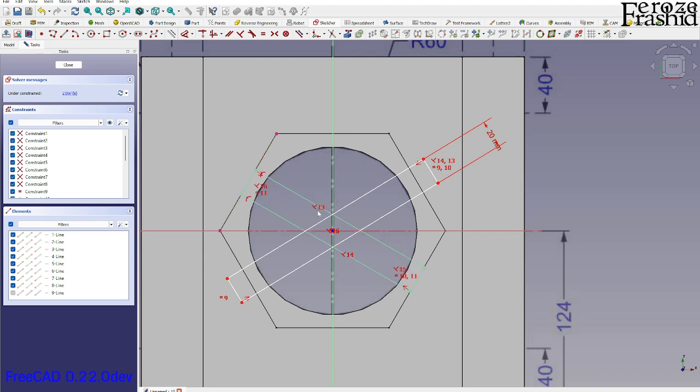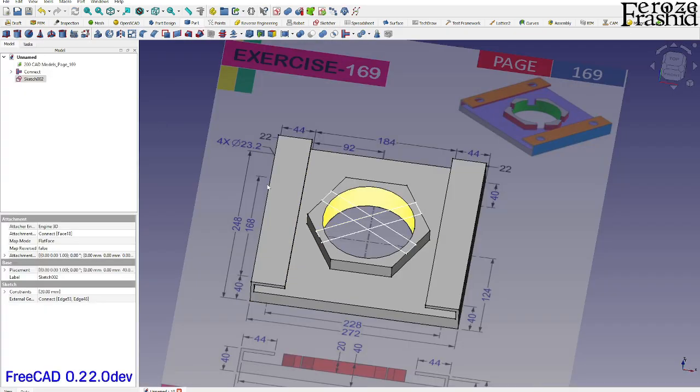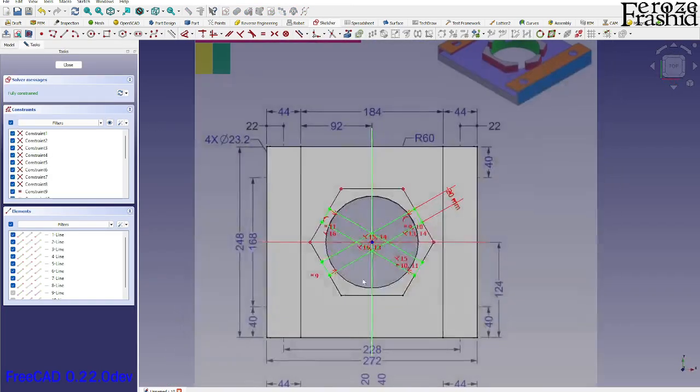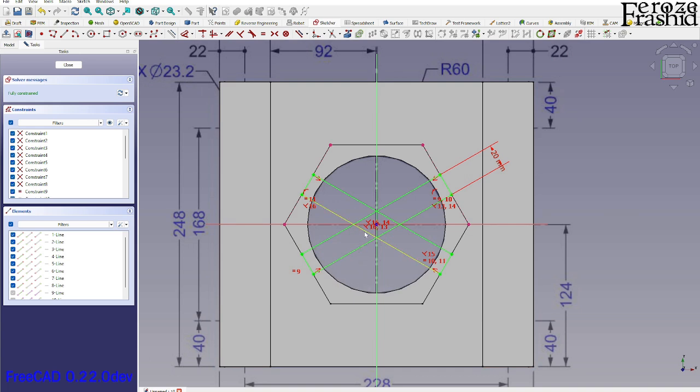Okay, see how it lined up. So maybe we need this reference line as well, and place these two ends on the line. That kind of places it in the middle, so we don't have to do this 30 millimeter on each side thing. Now this is what we need, but the problem is it's not closed.